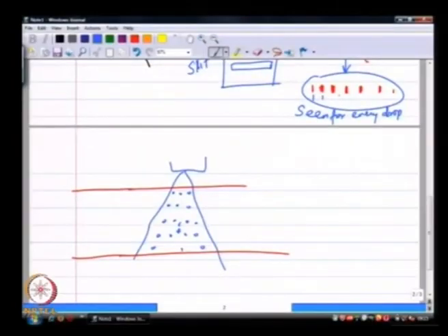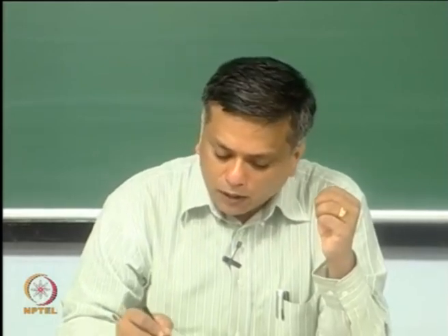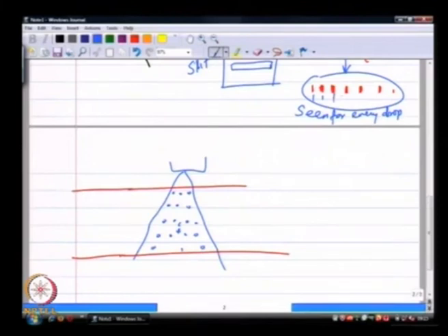Now, like I said, if you do the optical wave transmission calculation through a spherical drop, you will find that this fringe spacing is not exactly uniform throughout, and that contains information that is specific to that drop, for example in terms of sphericity, or a difference in the refractive index of the drop.